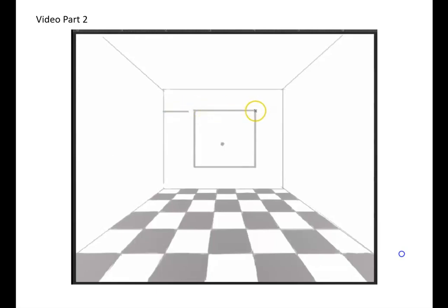So what you can see, I'm drawing transfer lines. If you draw transfer lines on the back wall, continue this line still. That's the wrong line. I told you, I did this kind of video kind of looking funny. The transfer lines must go all the way to the corner. So you transfer the height of the window to the side walls.